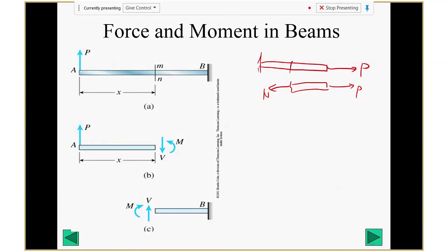Okay. Now, what about this situation? If you have a beam, the force is applying this way. What if I cut it, let's say I cut it here. Randomly, I cut the location. Right? Okay, cut it here. Then what kind of force are you going to have at that cross-section? Okay, you say shear, right? So like you show here. This is a free body diagram. So there may be shear, and there may be moment. Okay, there may also be a force in this direction, right? But I can prove it's 0.